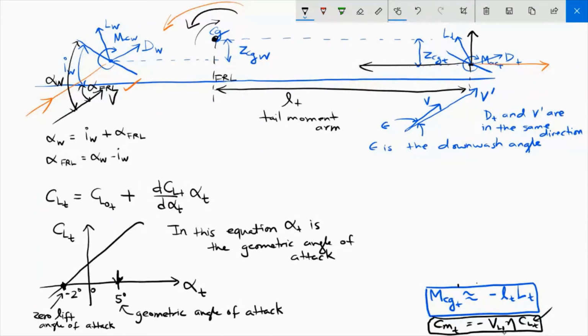So this is 7 degrees absolute angle of attack, because we are measuring this angle relative to this minus 2. So we have decided to refer to minus 2 degrees as the starting point. Okay, so when you measure the angle from the zero lift angle of attack, then that angle is your absolute angle of attack.